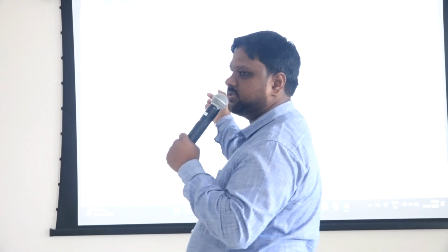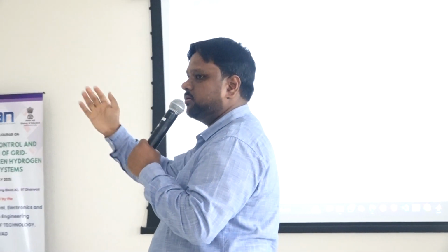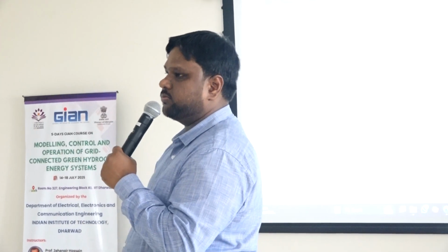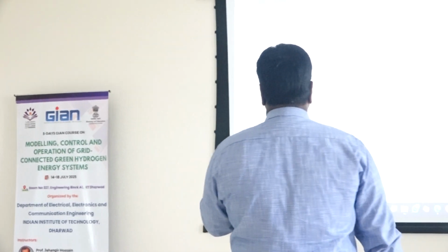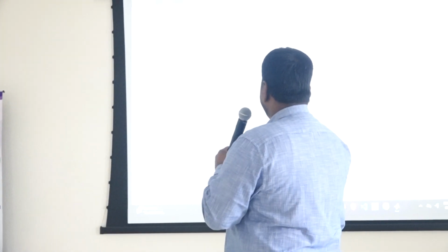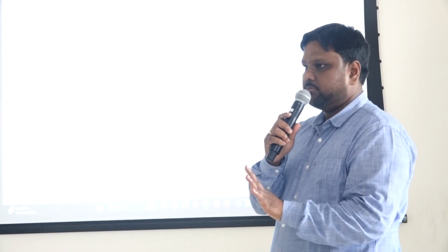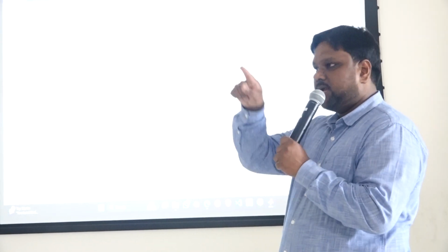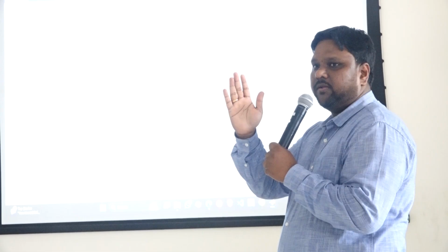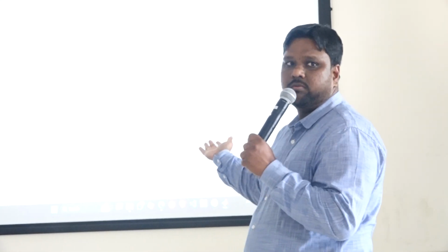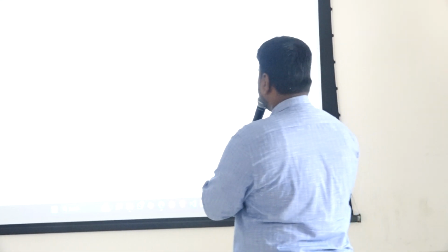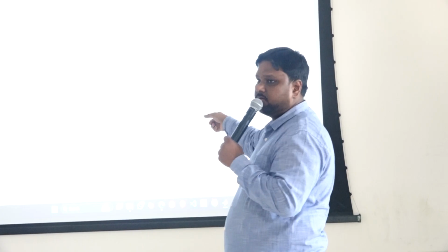We will show the pulses. Once we give it, we will plot the pulses, you see which is going where. So you can double click on pulse generator. And the switching frequency will be the same. Only one pulse we are shifting by angle phi and giving to switch 5. So that angle we will give here as phase delay.